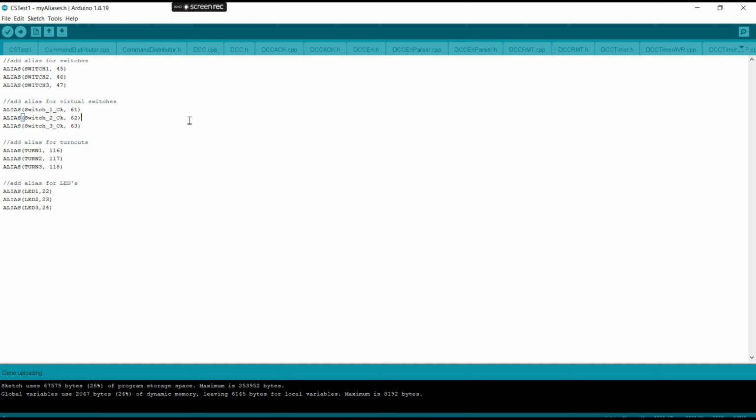It's basically just setting an address so you can fool it into thinking there's a switch that's on or off. If you're using I/O expanders, just be careful because you have addresses that you assign to the I/O expanders, and your virtual addresses need to be something that does not exist anywhere in that hardware. So that's the thing to watch. These need to be software-only switches, sensors, basically.